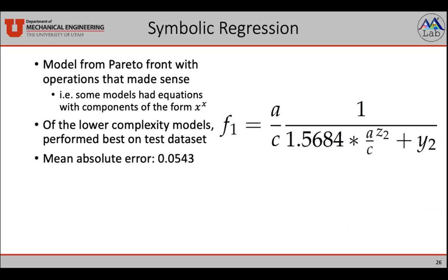One thing of note is that this equation was only dependent on a over c and Z2 and Y2, which are the Z and Y components of that crack growth path. We expected this to be dependent on a over t and the initial crack insertion orientation because of similar stress intensity factor equations in literature.